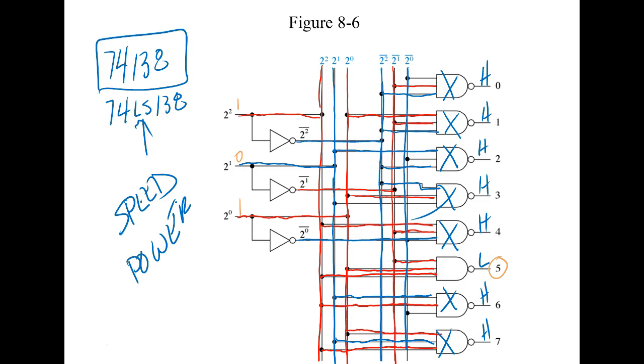So what is fan out? We don't see it in data sheets. So fan out is the number of inputs this gate right there could drive of the like family. So standard TTL, this guy has a fan out of about 10 gates, 10 inputs. So it means a 74138 could, and that's a rule of thumb, you'd have to actually look it up, drive the inputs of 10 gates. I'm sorry, 10 inputs.